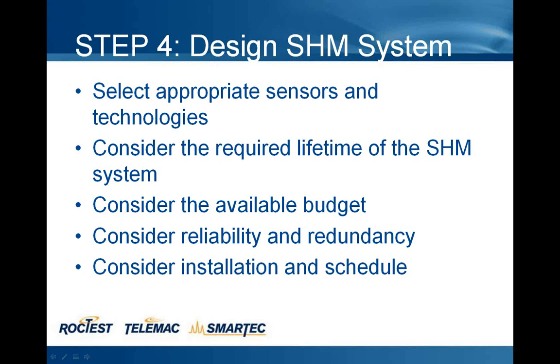Also, it's important to consider reliability and redundancy, which sensors are very critical, and maybe we have to plan to have certain redundancies, so I have more sensors so that if some fail, there will still be enough to carry out the analysis. And also we have to define if the monitoring system must operate during 1 year during a critical construction phase or must operate for 50 years. This will lead to different designs of the monitoring system.